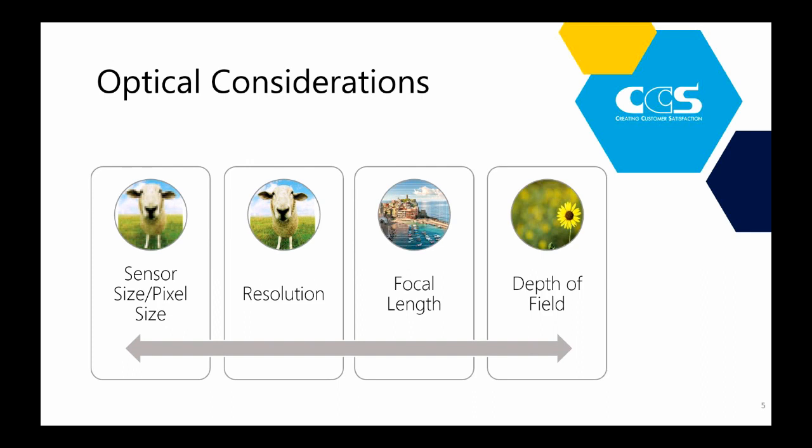For the focal length, there are often multiple options when choosing the appropriate focal length. A good rule of thumb is to not get too close to your object. Fields of view that are too large relative to a lens's working distance place excessive demands on the design of the optics and can decrease the system performance. We usually recommend that a lens be chosen so that the working distance is roughly 2 to 4 times as long as the desired field of view is wide. That's just to maximize the performance while minimizing the cost and complexity.